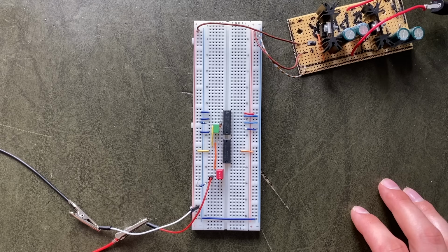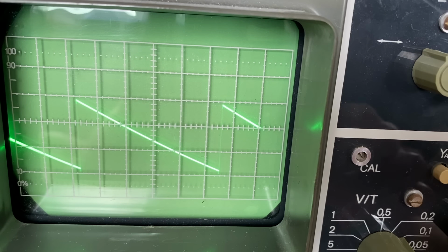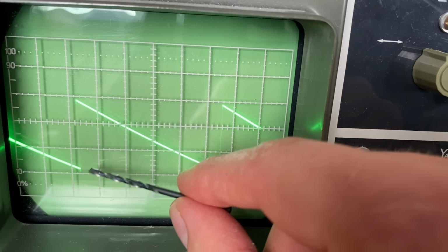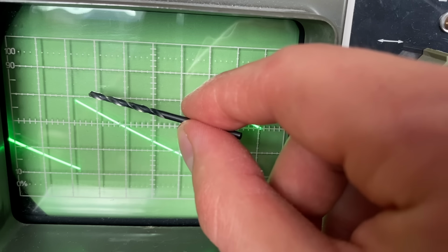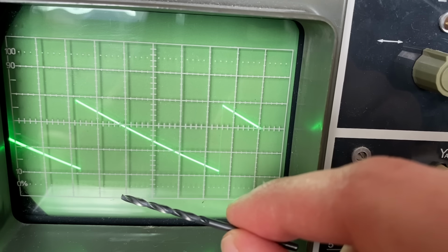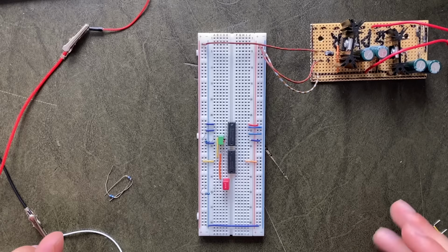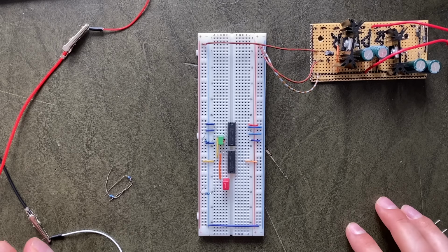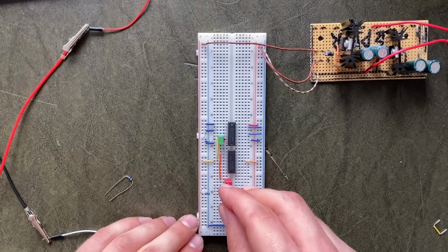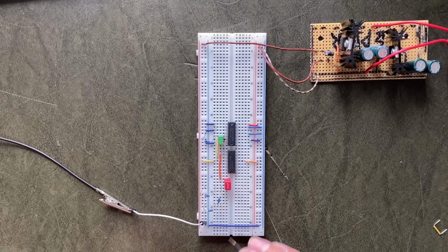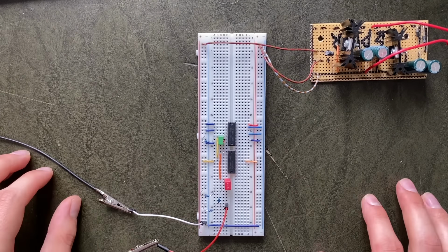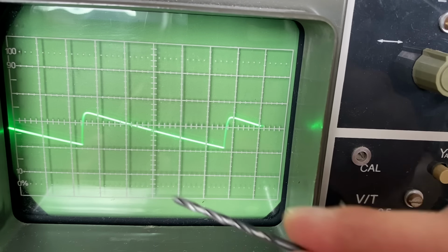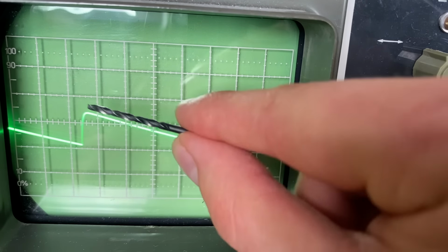To see if that works, let's first check the size of our original oscillation on the oscilloscope. So you can see that the oscillation is between the bottom of this square and the top of this square. So we could say that it has a height of 3 squares. And now I'll set up our voltage divider with two 100k ohm resistors. And I'm expecting to see the size of that oscillation to be cut down by half. Yeah, that looks about right. Now the oscillation is about 1.5 squares high.